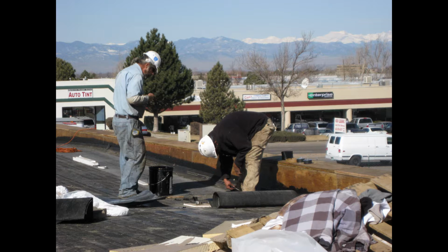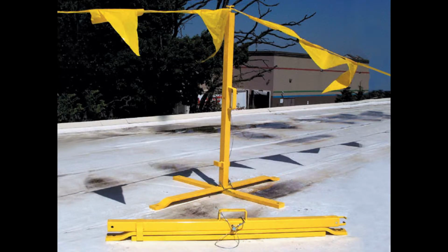Mechanical equipment shall not be used or stored in areas where safety monitoring systems are being used to monitor employees engaged in roofing operations on low-slope roofs. No employee other than an employee engaged in roofing work on low-slope roofs or an employee covered by a fall protection plan shall be allowed in an area where an employee is being protected by a safety monitoring system. Each employee working in a controlled access zone shall be directed to comply promptly with fall hazard warnings from safety monitors.